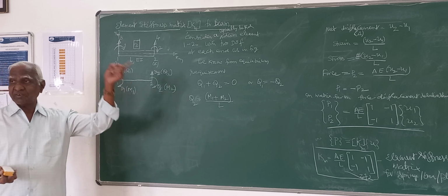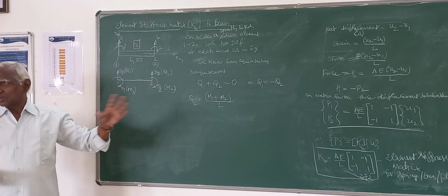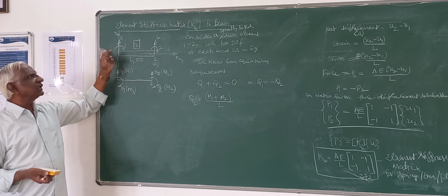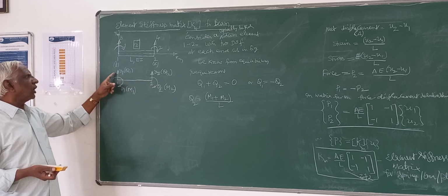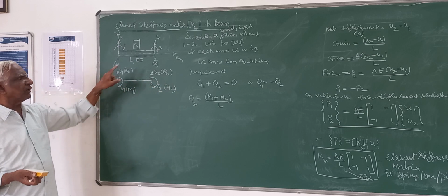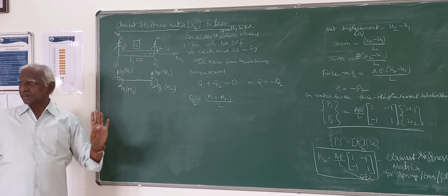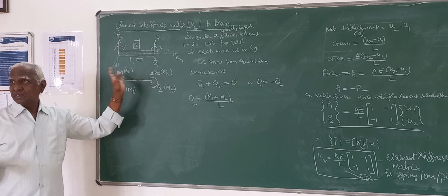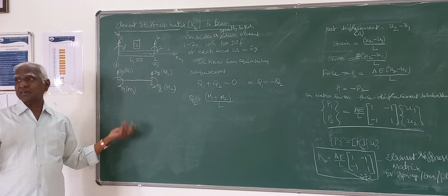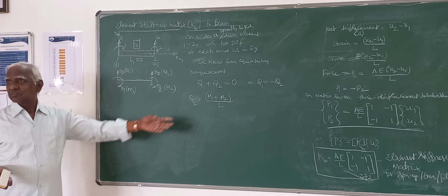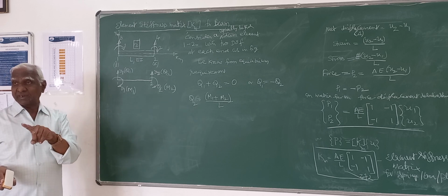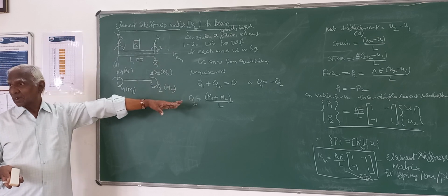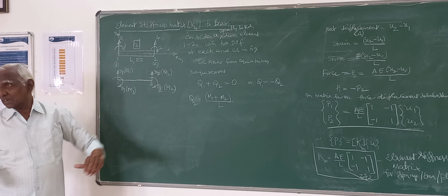Of that, again, I defined this when talking about the flexibility matrix. Now I am dealing with only the stiffness matrix. So in the stiffness matrix, it is displacements, all the 4 displacements V1, theta 1, V2, theta 2, that you can treat as independent, because the equilibrium requirement doesn't say which is independent. All are treated as independent. That's why I told you repeatedly, stiffness is the best suited one. Here the dilemma will come, which to select. Any selection can be made.